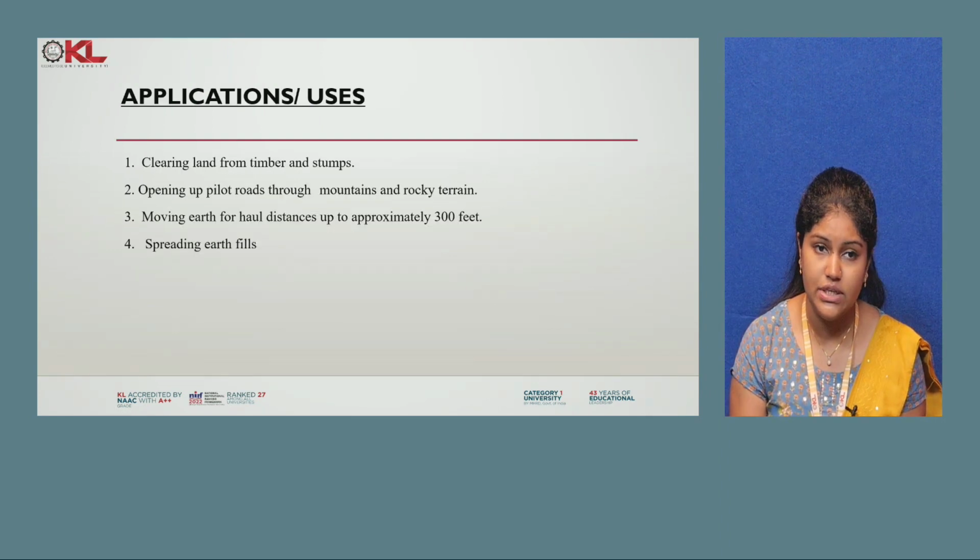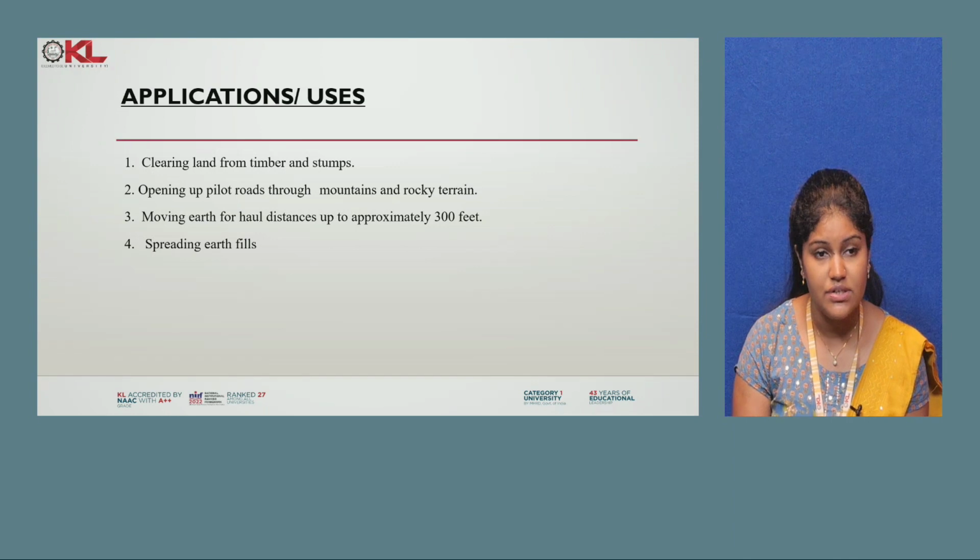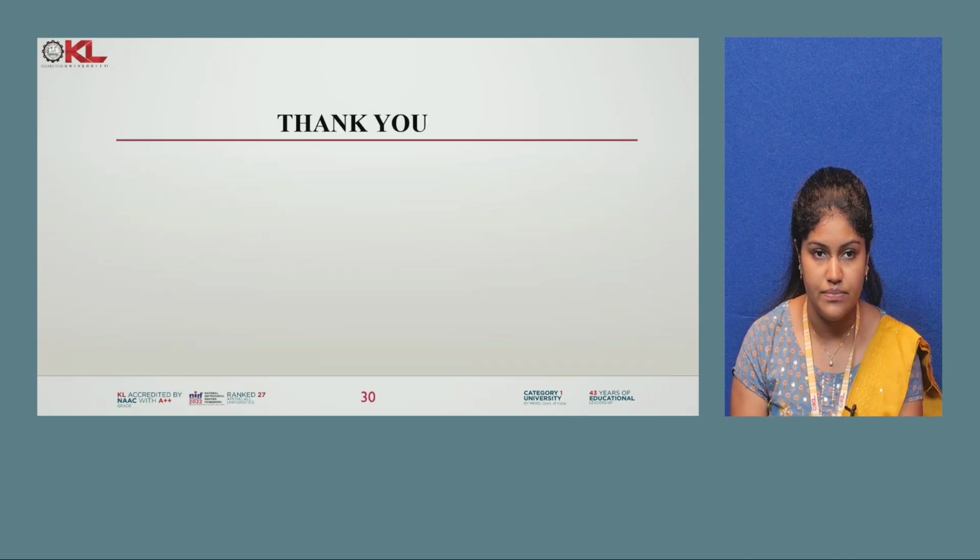So what is the application of a bulldozer? It is for clearing land of timber and stumps, opening up pilot roads in mountains and rocky terrain, moving earth for haul distances up to approximately 300 feet, and spreading earth fill. This is the application of a bulldozer.